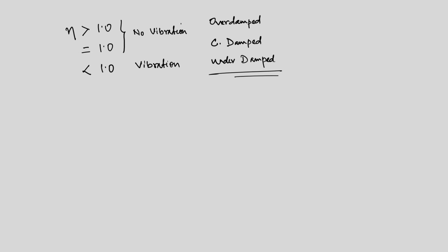And from the mathematical solution, what we have noticed is that in the third case we have roots which are complex in nature, and because of the presence of damping we have these complex roots, and the nature of the vibration is periodic, and then as time progresses, it starts the vibration, then gradually comes back to 0. So, with that, let us close here our discussion on damped free vibration.